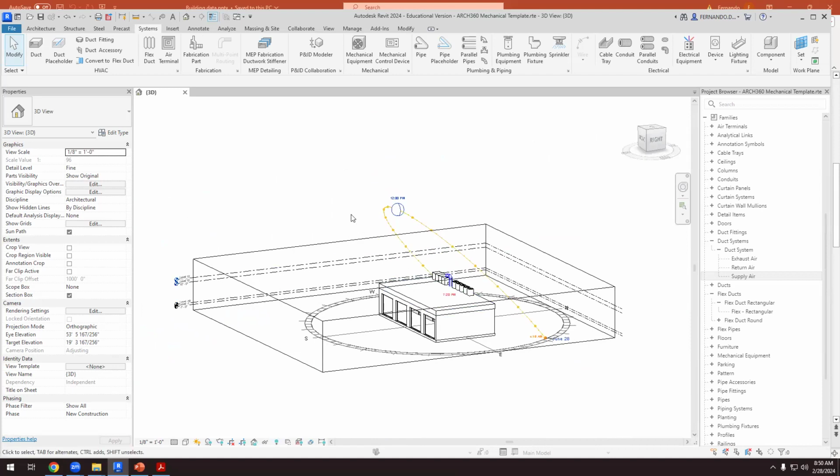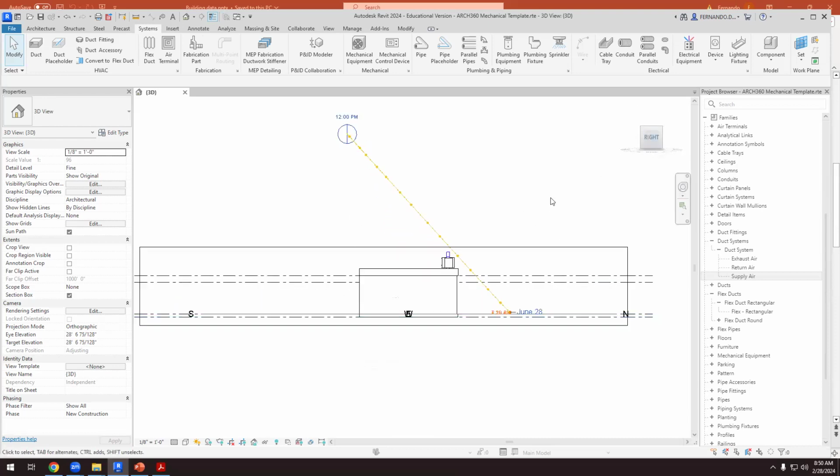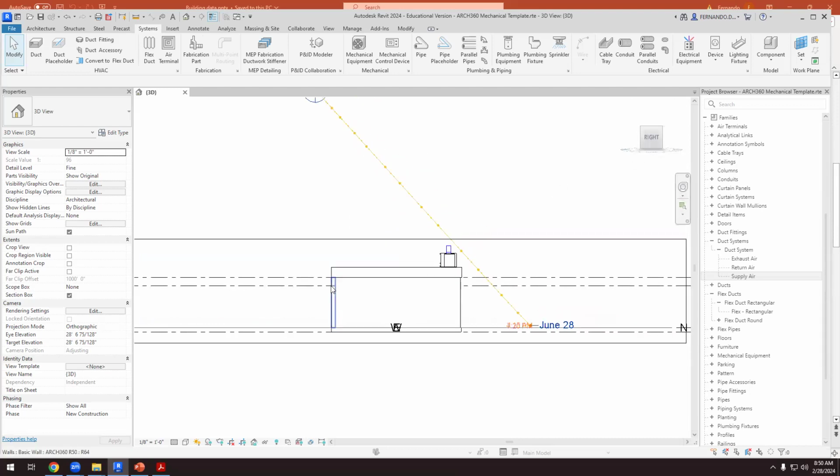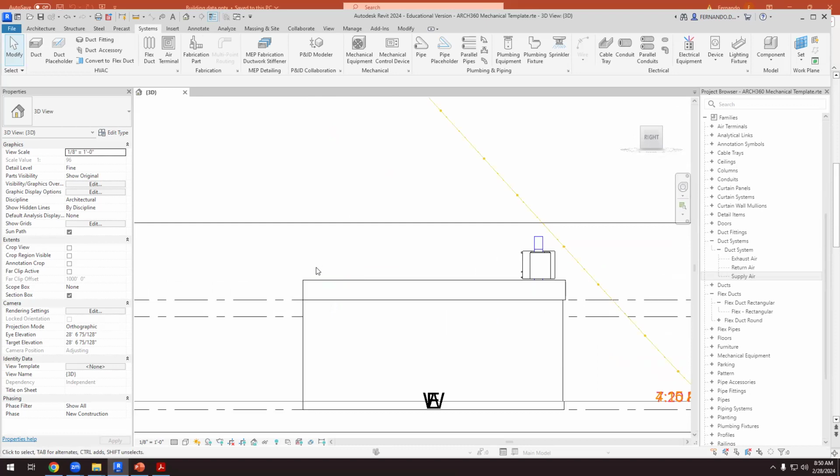We don't have to insert a PV panel family. We're going to use the easiest option. We're going to create a tilted roof, and then we're going to understand the amount of sun that we can get, or the amount of electric energy that we can get if we placed PV panels on that roof. Okay, so let's do it. We are in this right view, okay? And now I need to place PV panels here. And the angle can be, we're going to try 30, and then see what happens.